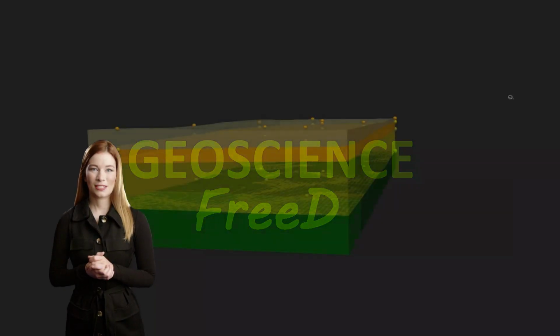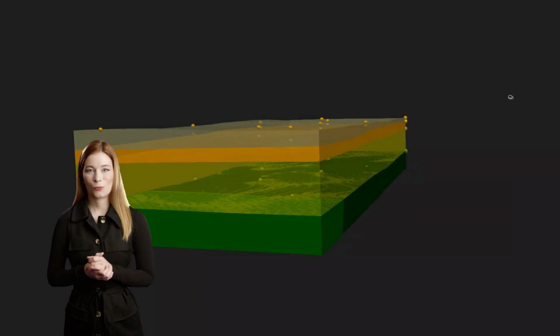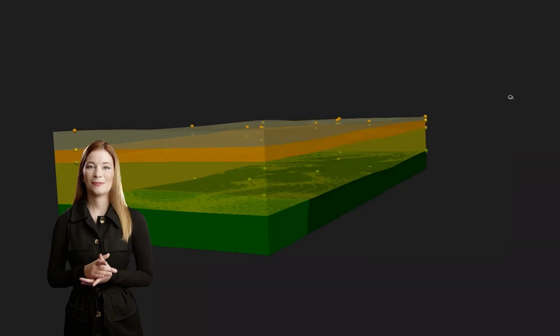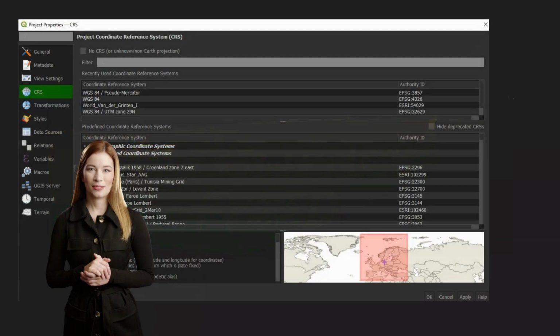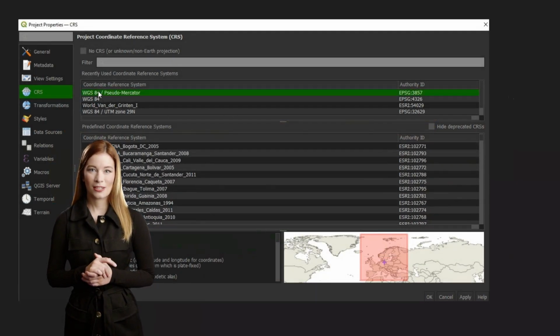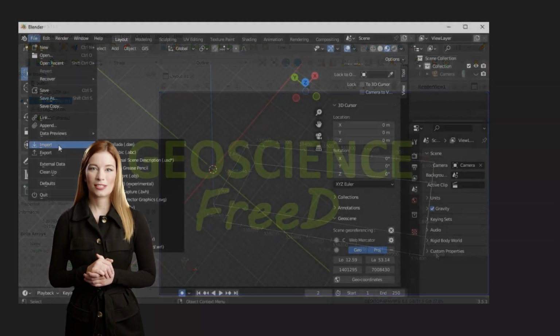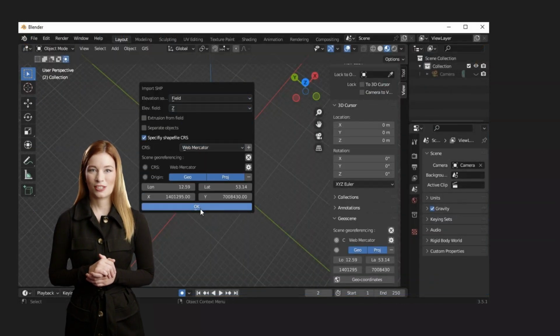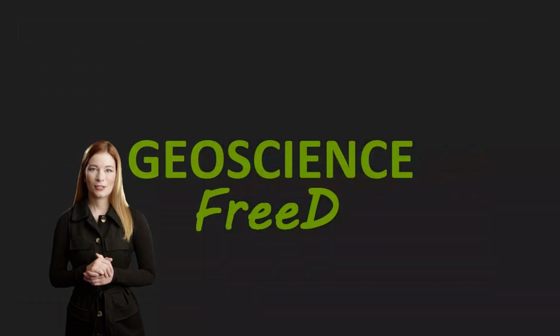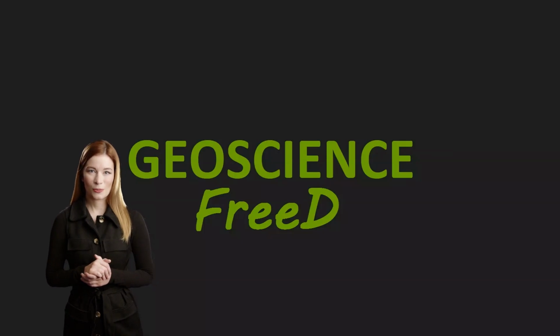Any data has to be positioned in relation to the Earth's surface, and while the Earth sadly is not flat, we need geographic coordinates or their projections. While GIS natively manages data in the whole range of frameworks and allows transformation from one to another, transferring it to other software for scientific modeling, animation, or geostatistics may introduce spatial distortions as they display data in the Cartesian grid. In this episode, we'll try to avoid such pitfalls, which could obviously result in financial and environmental losses depending on the type of projects we are working on.